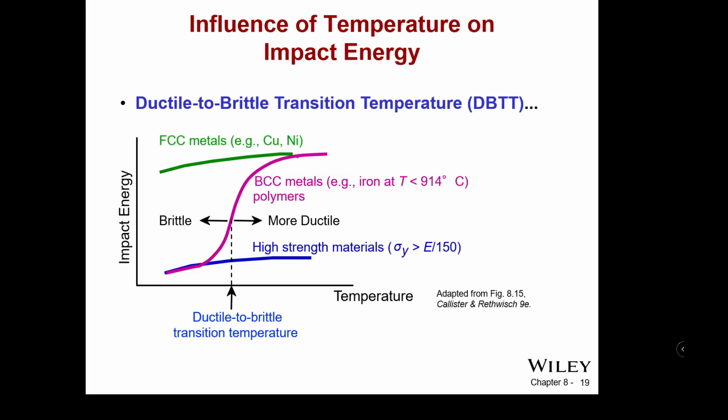The higher impact energy is the stuff that has more physical dimensions to be able to absorb all of that energy into. So they bend and move a lot before they actually fail. And that's why things like copper and nickel, so metals that are softer, are behaving more ductile-like, which is why that's to the left side. So the brittle materials are below.